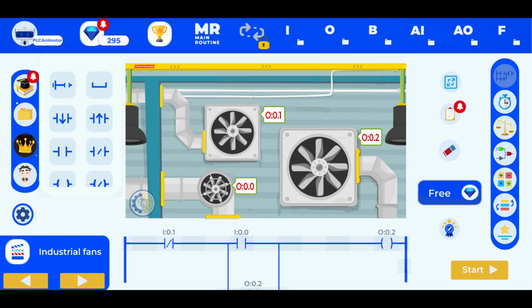So behind our buttons or our pulse, we're going to input our blocks for normally open or normally closed. When they are emergency stops or any device where we have to stop our machine, we generally recommend using normally closed contacts. And we need to make them match with our physical PLC inputs generally. Okay? So then, knowing all this, now it works the other way around.